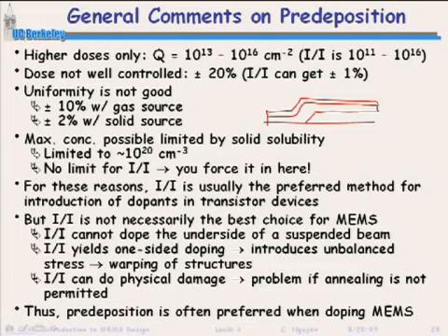If you have a stress gradient across a beam, that stress gradient is going to cause that beam to bend, because where that stress gradient is, there are forces at the top that are pushing out. Those forces are not there at the bottom. And so those forces pushing out are going to force that beam to try to expand at the top, which means it's going to bend down. Different dopants will make you bend different ways, but this is one reason why you don't want to ion implant your MEMS structures. You can get warping because it's not a symmetrical doping of this structure.